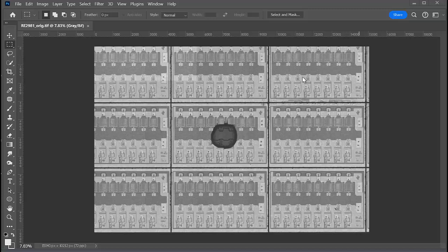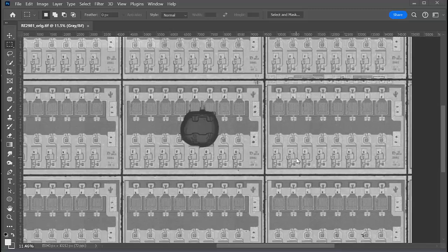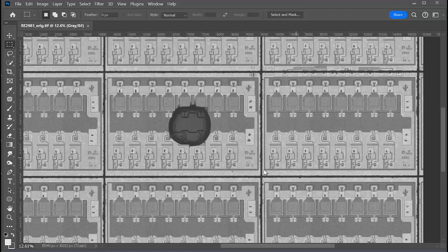You start with an image of our die. In this case we have multiple die, and we're going to clip to the lower left of our die so that becomes our reference point of 0, 0 in the GDS2 file when we convert it. If we know that reference point and we know the length and the height of this die, then we know exactly where the corners of the die are, and our new feature will center on the die outline and not on the extents of the die pads.